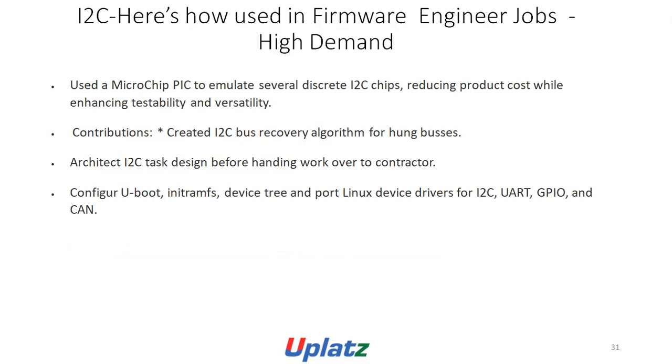Contributed by creating an I2C bus recovery algorithm for ANG buses. Architect I2C task design before handing work over to a contractor. Configure U-Boot, device tree, and port Linux device drivers for I2C, UART, GPIO, and CAN.